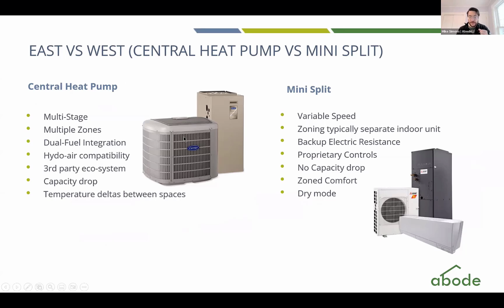With this type of equipment, you can put on Honeywell zone control and can have first floor, second floor, third floor, all independently heated from this one unit. You can have dual fuel integration, where you can have a high efficiency heat pump that's sitting on top of a natural gas or an oil fired furnace.